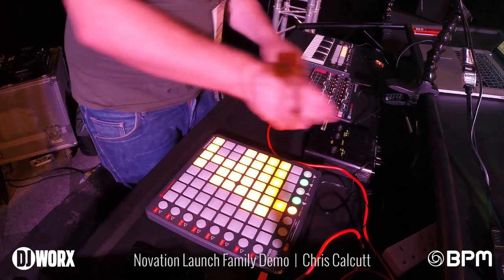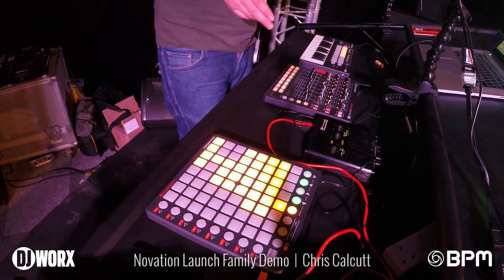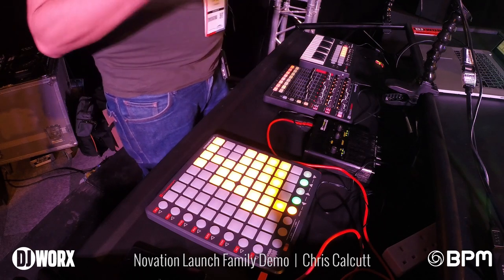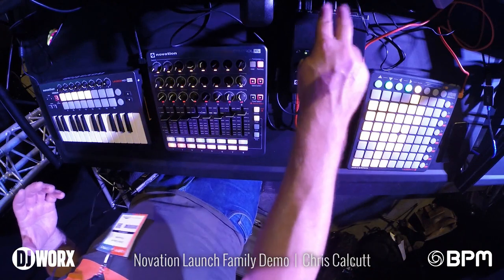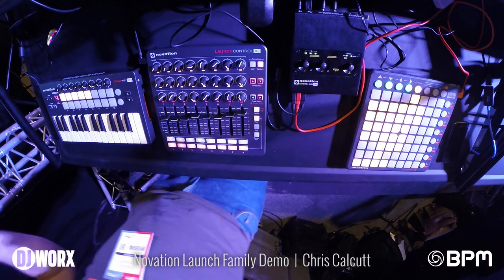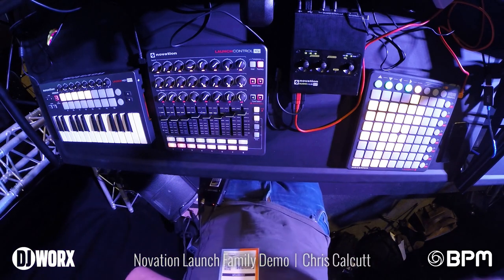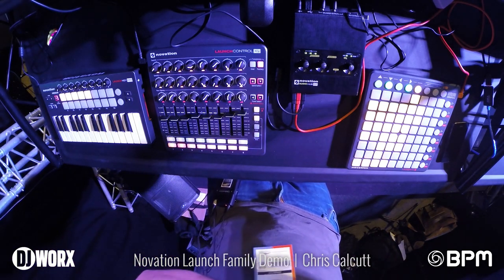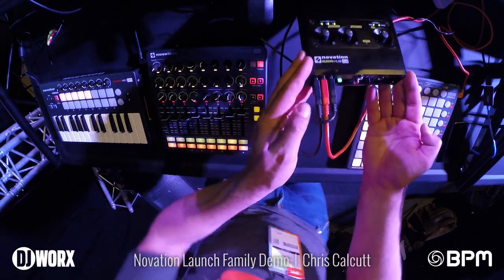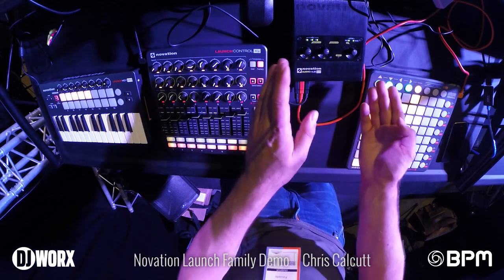There are just a couple of other quick features on AudioHub 2x4. As I say, it's 2 inputs and 4 outputs on the interface. And with having 4 outputs, that's a very useful thing from a digital performance point of view. In this situation, I have my main outputs feeding the PA system that we have here. But what if I'm working in Traktor and I want to set up a Q headphone mix? I can easily do that by, within Traktor, choosing outputs 3 and 4 for the Q mix. I can then plug my headphones into the headphone socket on the front panel of the device.